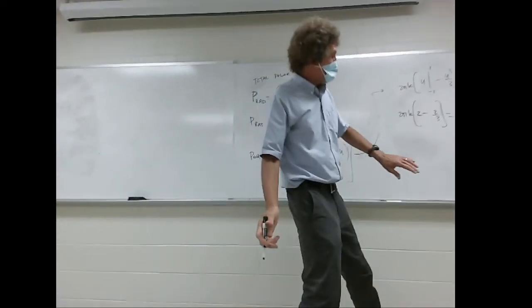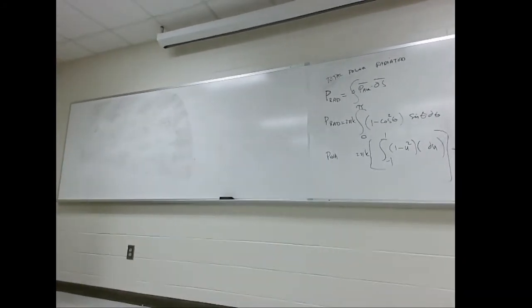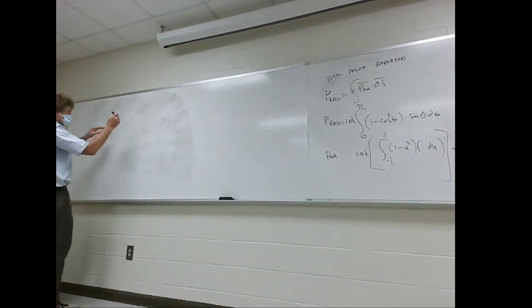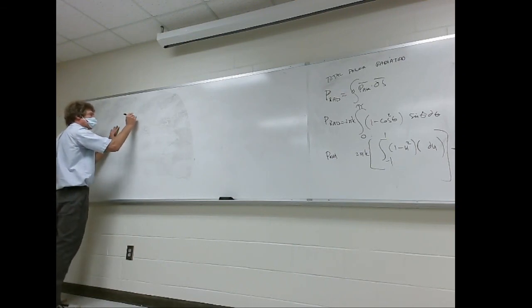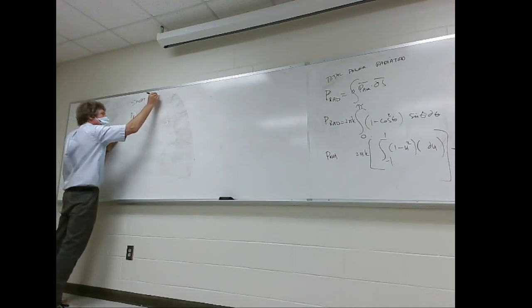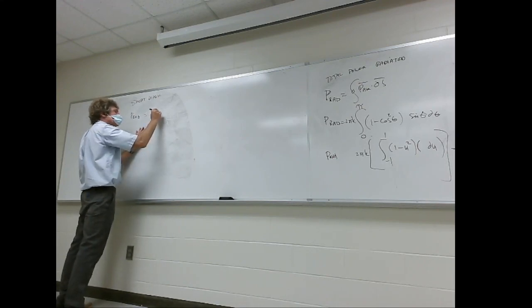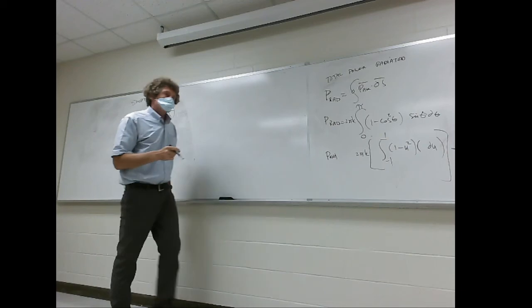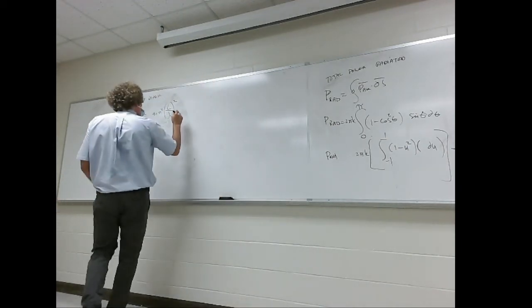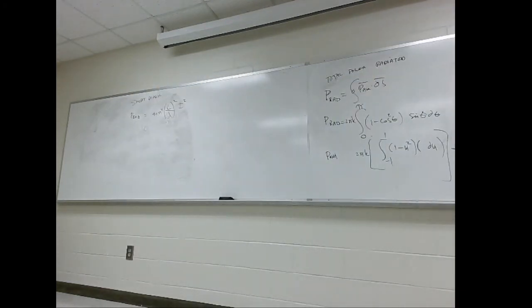So if I took K and plugged it in here, I want you to listen to me now. And you turn the crank, there are a lot of cancellations, you would find this. The total radiated power, and this is from a short dipole, would be equal to 40 pi squared, and then it would be the length of the antenna over lambda squared, times I squared. And this is in Dr. Wentworth's book.